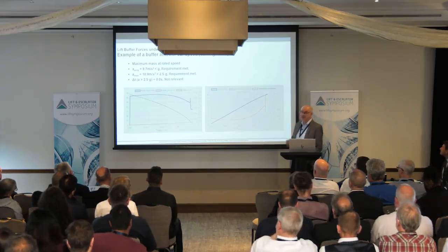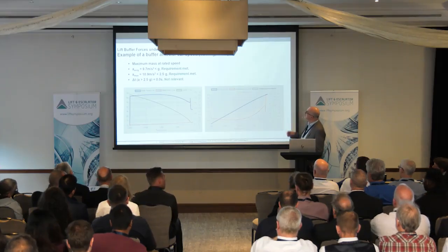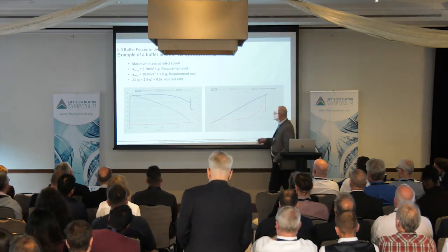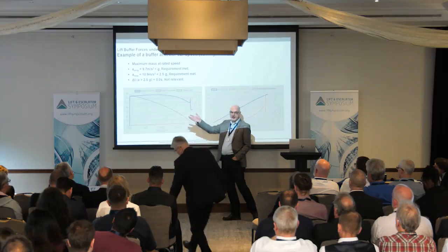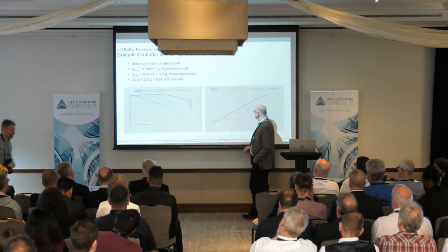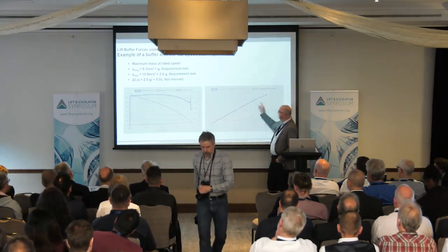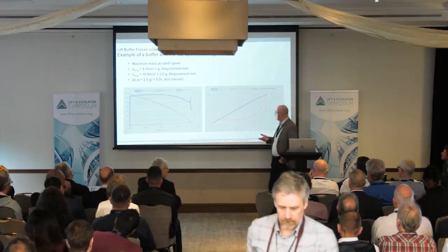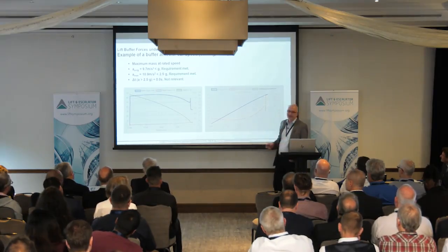The first situation is the lift at 1 meter per second. Just to explain it once, this is the buffer force at the backstroke, the speed during the buffering process, the red, the deceleration, blue, the energy absorbed by the buffer, and yellow, you can see the time lapsing during this process.